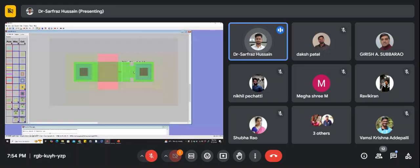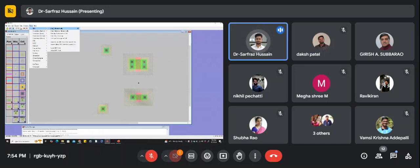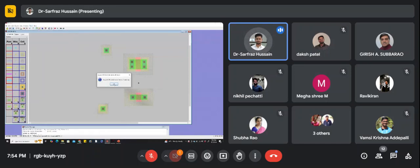So here I have brought it to 1 almost. Okay, so I have brought almost to 1. And now see, we have placed this one. Now if there is any mistake in placing this one, it will show an error. So what you can do is go to Tools, then Check Hierarchy. So you can see it is showing 2 errors, so we can check these errors.